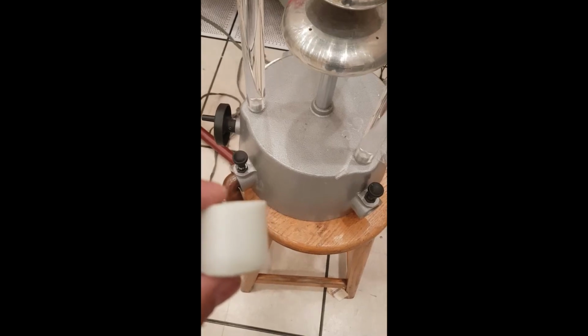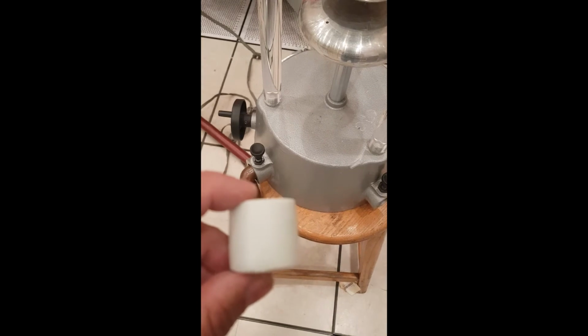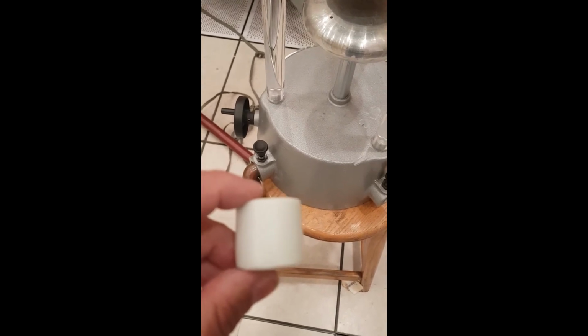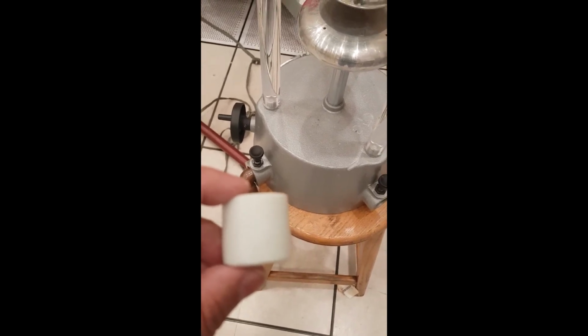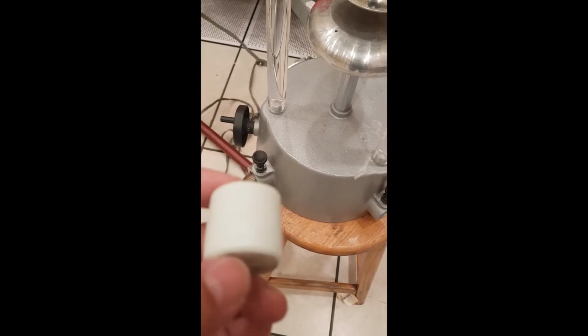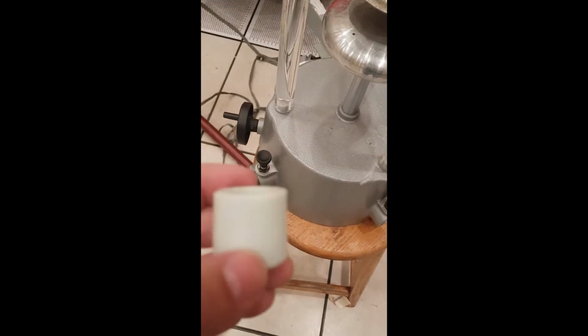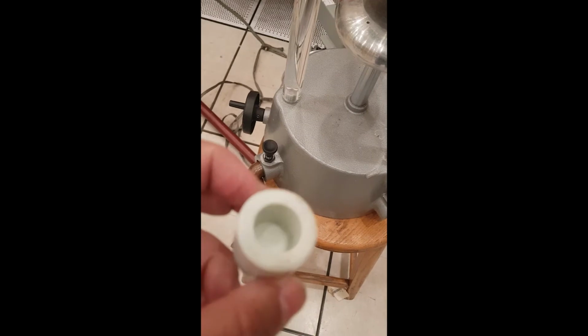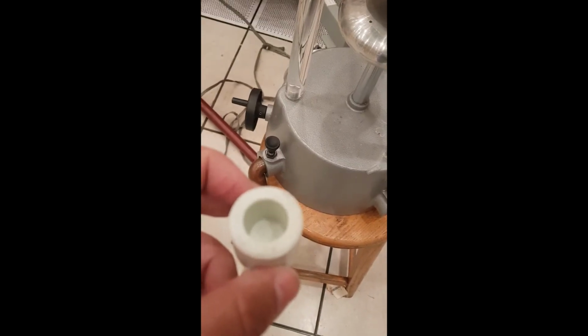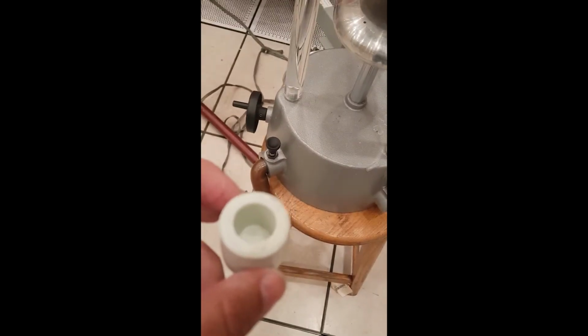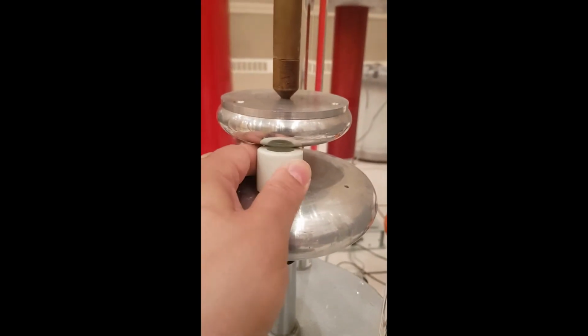In this video, we want to learn about void discharge. Whenever there is a void inside an insulation system, we want to see what is the pattern of such discharge. So basically, we have here a ceramic material, and you can look here, there is a hollow, there is a void inside this ceramic insulator. So I will put it between two parallel electrodes like this one.